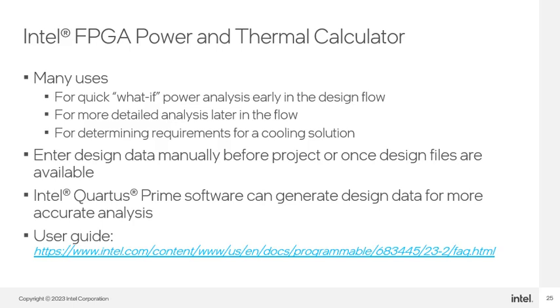This also provides a more accurate power analysis since the information comes from the design itself instead of your own estimates. The PTC also provides information about device thermal management and cooling solution requirements based on a selected maximum desired junction temperature. For detailed information about the PTC, see its user guide. The latest version as of this training is linked here.